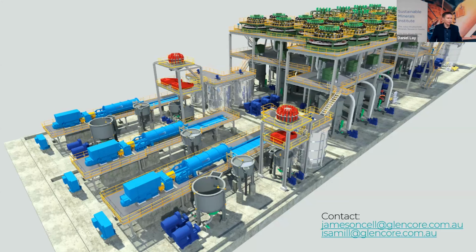Then with regards to liberation and textures, I don't know that we have a lot of data looking at texture as an actual variable. But I would say that it's basically an artifact of floatability, and whatever that would constitute, whether it's liberation or size or texture or collector coverage, you're basically choosing the most floatable material first, and then gradually adding less and less floatable material as you go on, using the froth depth as your control. Yes, the froth depth and the froth washing, and the air rate as well.